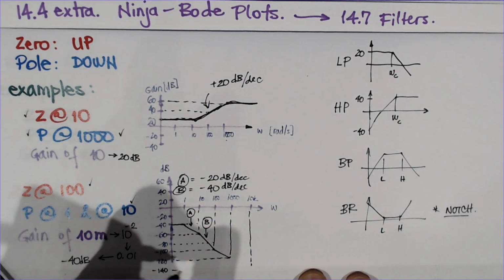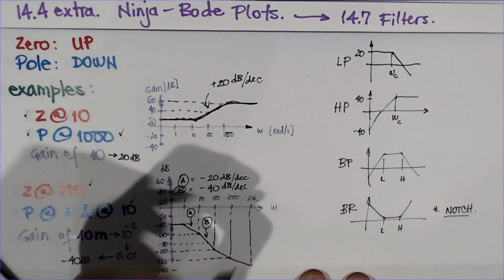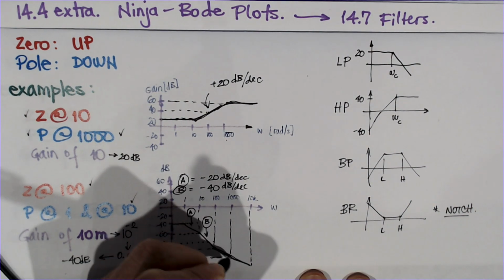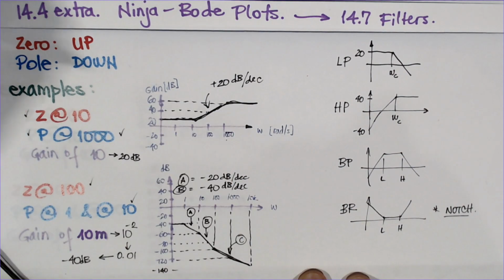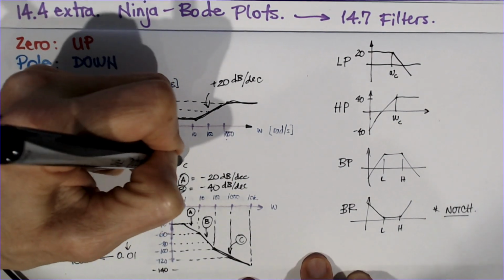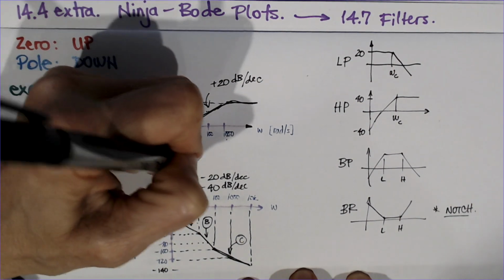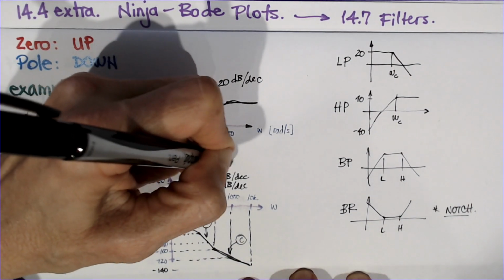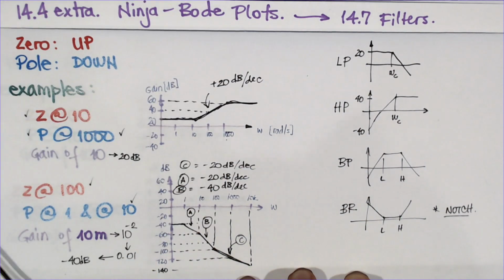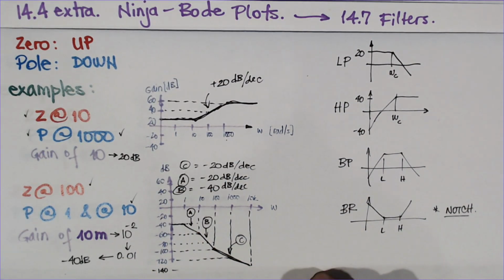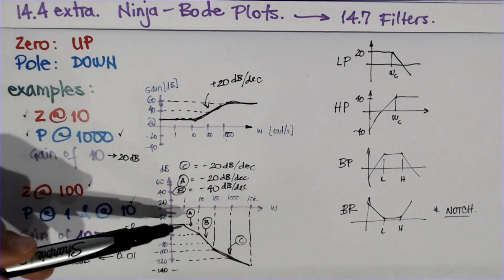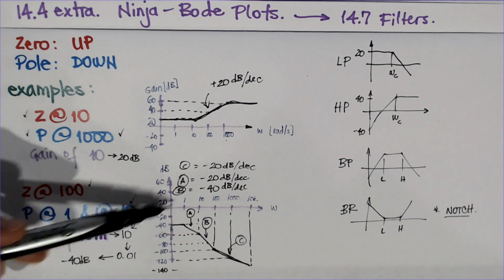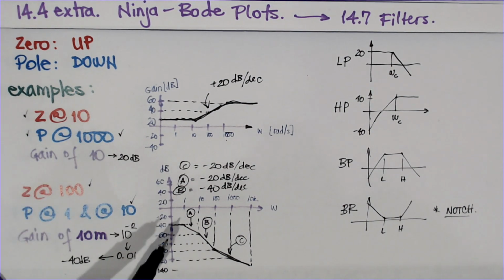I don't know if you can see there. So this is supposed to be a straight line. Need to go back to elementary school to draw. So my C phase there is again minus 20 dB per decade. And it keeps going down. So really these higher frequencies here will never get amplified. Of course, the whole thing was not amplified anyway, so you're just putting a 0.01 gain until 1 radian per second. After that, there's really no signal at all.